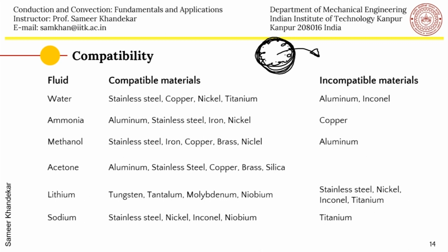And this hydrogen gas, as you know, will hamper the heat transfer, because it will go and collect in the condenser area, which is the coldest part of the whole device, and it will block the condenser. And condensation heat transfer is very severely affected by the presence of non-condensable gases, and therefore aluminum-water heat pipes are not possible.